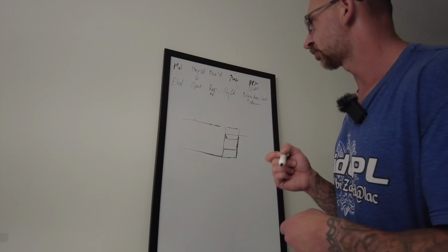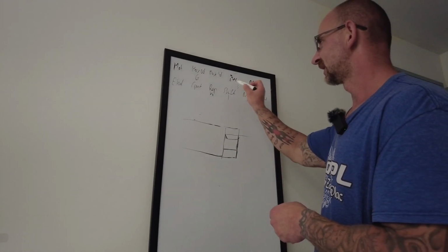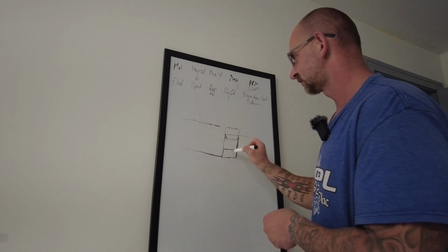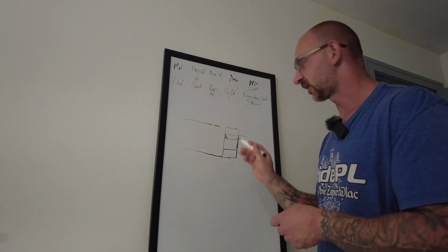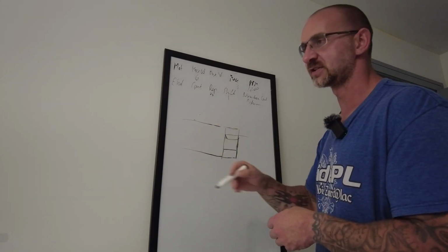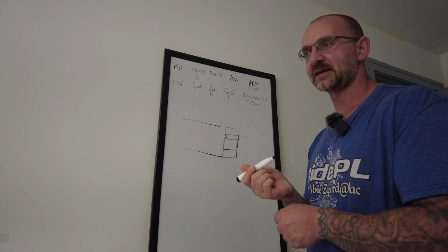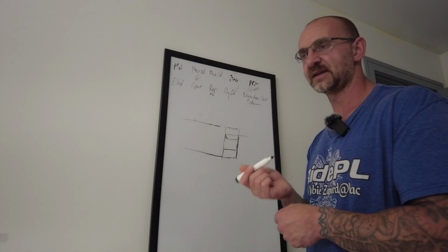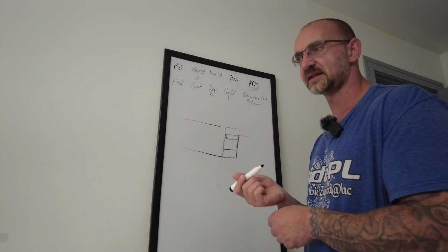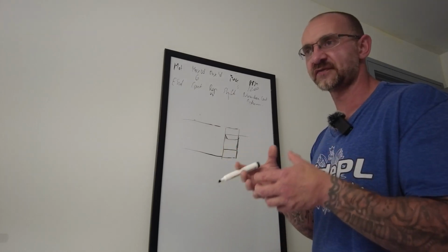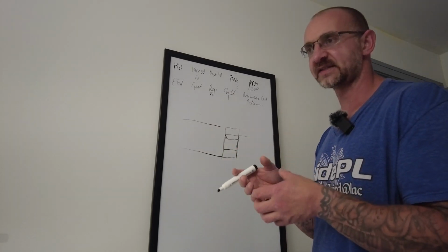Technically the problem was the length of the part. If you're cutting 5 parts, you have to give the accumulated length, so 5 inches, and always add an extra. My total material length was 4 inches, but the actual accumulated was 5 inches, and that 1 inch messed up the clearances.